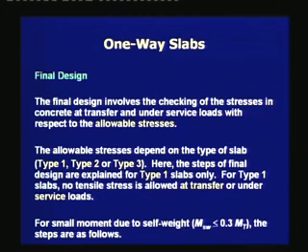The allowable stresses depend on the type of slab, type 1, type 2 or type 3. Here the steps of final design are explained for type 1 slabs only. For type 1 slabs, no tensile stress is allowed at transfer or under service loads.